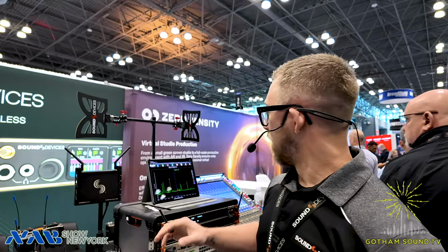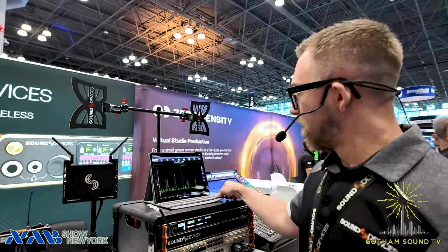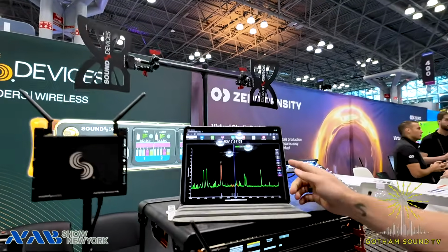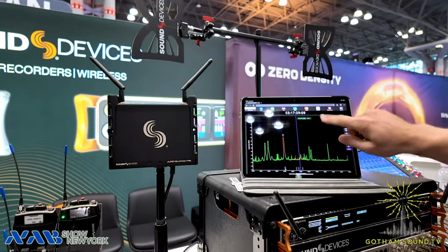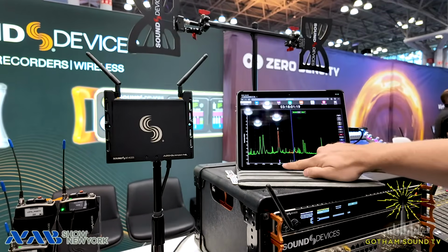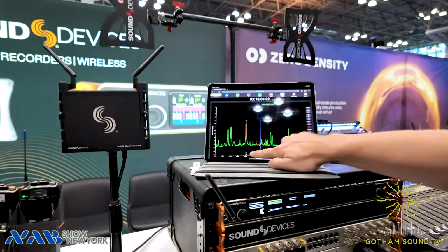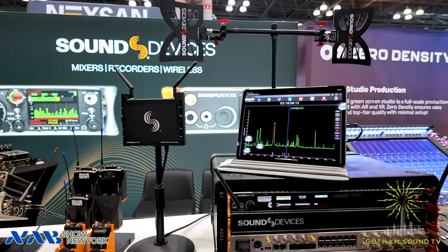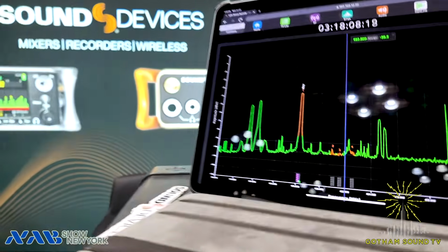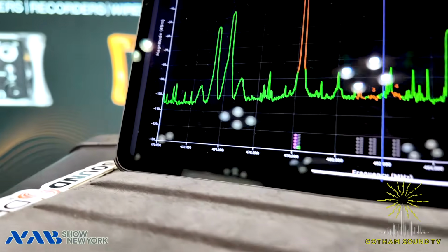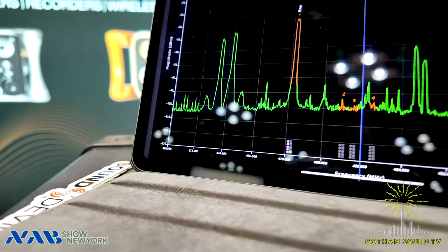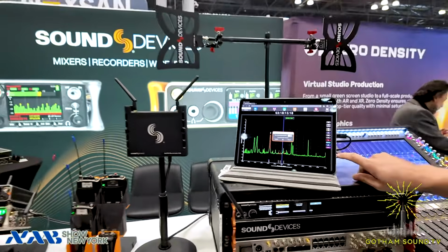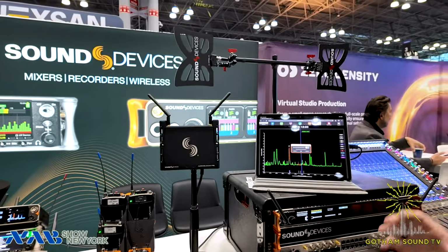Nice. And then our RTSA screen got a little bit of an upgrade here. So now you'll notice this is a carrier, and this is my microphone that's live right now. But we also have Q and audio meters as well as battery that show up on the RTSA screen. Yep. And so we've got that as well as exclusion groups. So now I can go ahead and add exclusion groups on my auto assign, so I can try to work around an appropriate band plan.